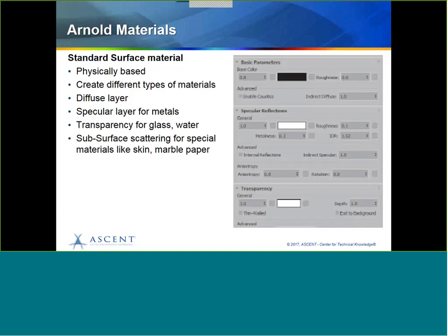A roughness value of 0 will give you a very sharp clear coat on top. What it does is the specular reflections are very small and very sharp, so it gives a shiny surface. If you want a rough material, for example concrete, or something else which does not have those specular reflections, then you need to increase the roughness here.